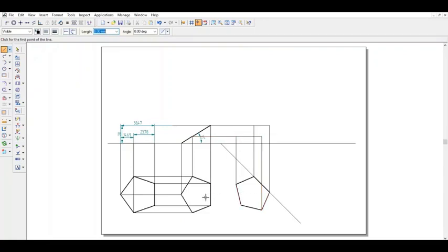And this corner I know that it is on the XY line, so just select on this XY line and project it till the XY line. Now join all the 5 points which you have got, all the end points you have to join. Then select the whole thing, change it to 0.5. This line you just change it to 0.13, which is the projection line. So you have to show the angles here, the angle of this one.